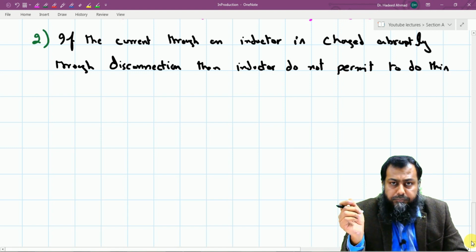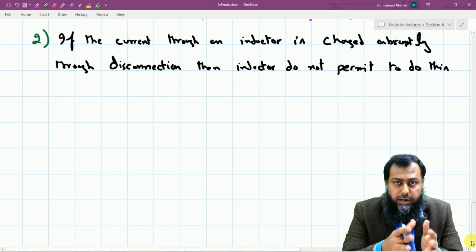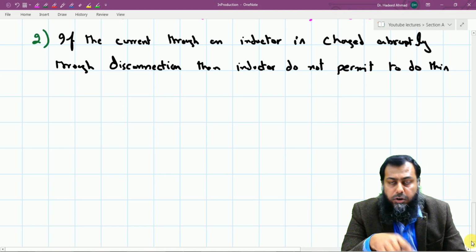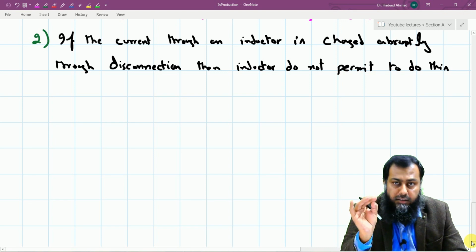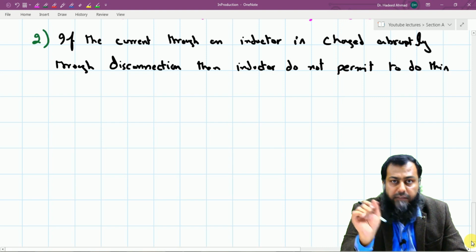You will learn in the advanced classes that this phenomenon, if we can control the amount of current, is very useful because it is used in vehicle ignition systems and in DC to DC converters and power electronics. Doing so uncontrolled means that the voltage spike will eventually damage one of the semiconductor devices connected in that given circuit.